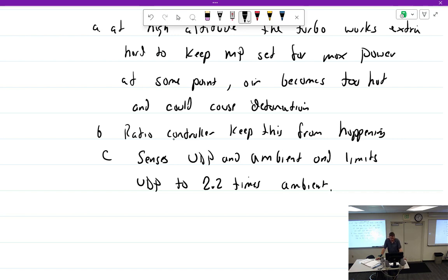All right. So, engine's off. We get in the airplane. What position's the wastegate in? No oil pressure says open. Right. Spring loaded to open. That's our default position, open. If everything went to hell, you don't want the turbo spooling up faster. So default's going to be open. That'd be safe, no turbo.